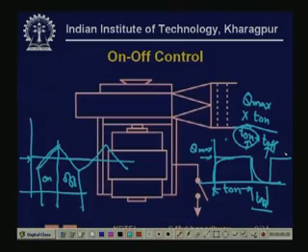You need nothing. You only need the motor and the fan. You anyway need those, but as far as equipment for driving the motor is concerned, you need nothing. You just need to switch on the motor and switch off the motor at a certain frequency or certain rate. For that also you need some equipment, but that is very simple. But this is hardly ever used because there will be flow pulsations, and these kinds of fans are typically used for industrial processes. We use them for cooling, for things like combustion.